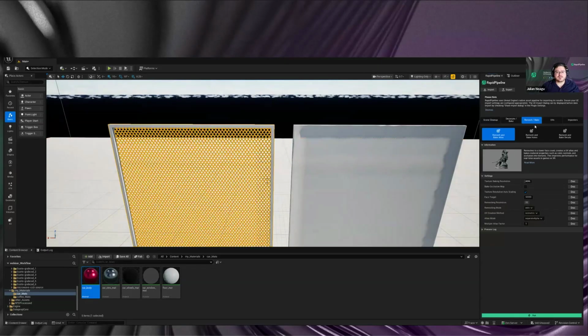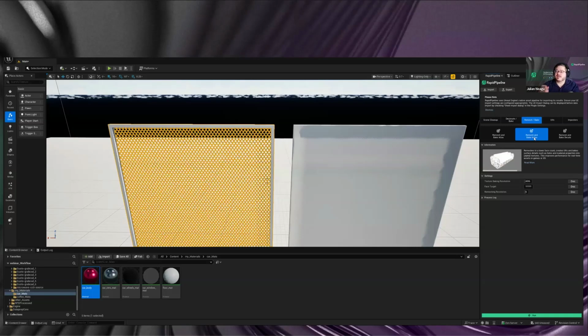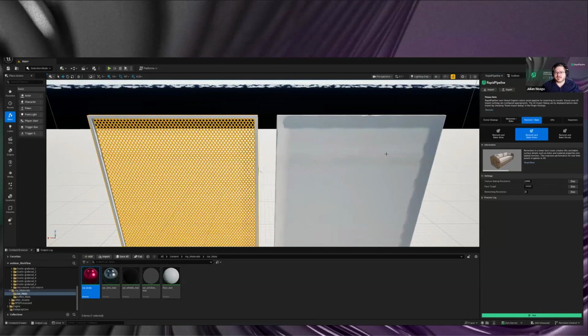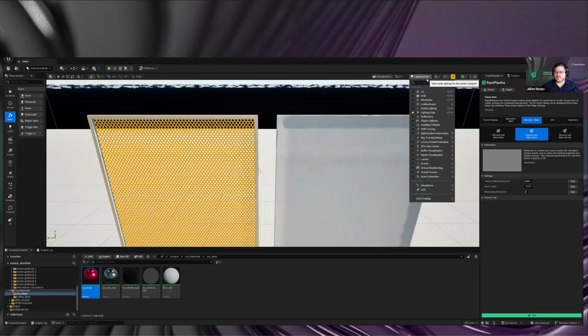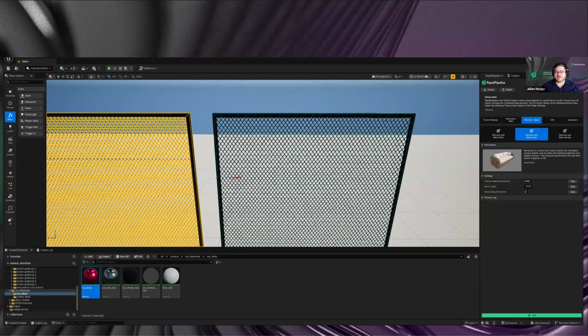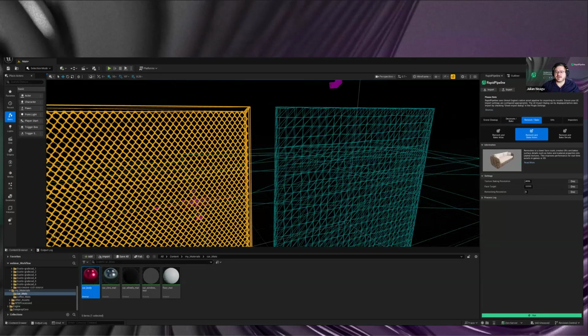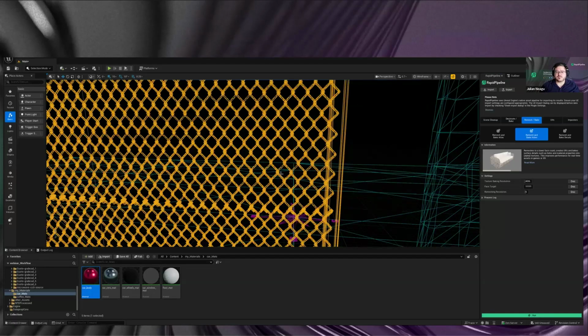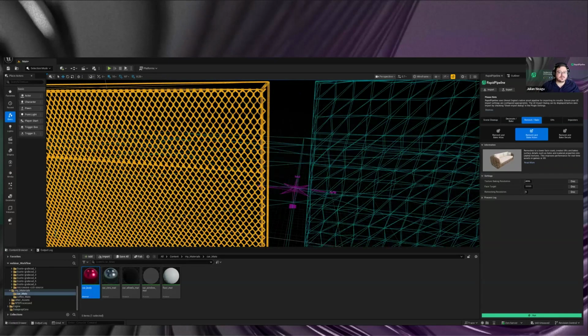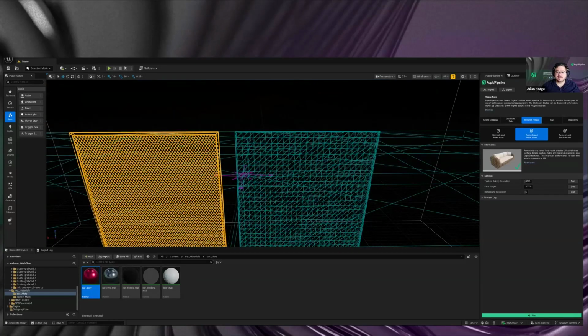So with the default option we have under remesh bake, we're actually using the remesh and bake holes feature. This is our alpha baking preset, which can not only shrink wrap and bake materials, but also identifies the gaps in the topology and then bakes those gaps into the alpha map as well. So in that case, what we did here is just a simple remesher. And if we go back to the lit wireframe one, or maybe the actual wireframe one is a bit better, you can see how massive the difference is in terms of the topology. So we got rid of completely all the little intricate mesh details here, and basically have a very homogeneous remeshed version.